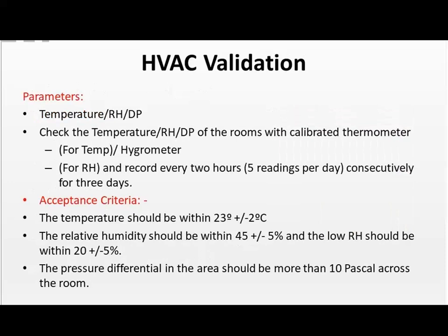So for temperature, relative humidity, and dew point, the ones that are certifying or requalifying your HEPA filters are going to check for temperature. They're going to check relative humidity and dew point. They're going to use calibrated thermometers. For temperature, they're going to have a hygrometer, and all of their equipment is going to be calibrated. They're going to check the relative humidity, and then we're going to make recordings and record the relative humidity every 2 hours for 5 readings. And they're probably going to do this for 3 consecutive days.